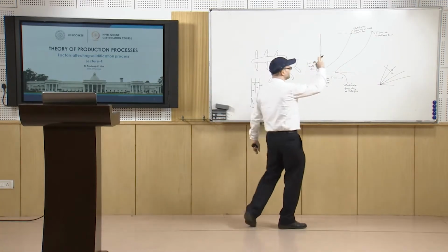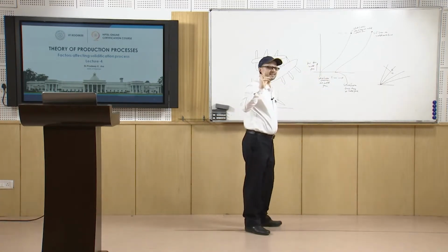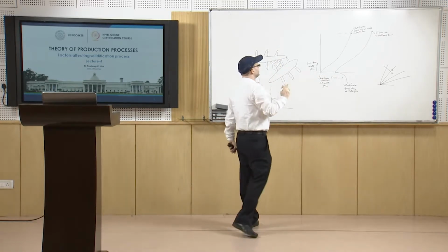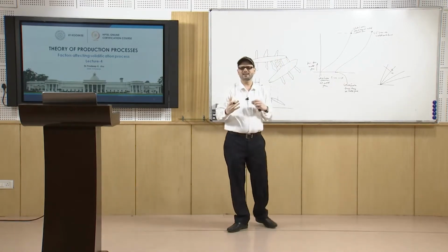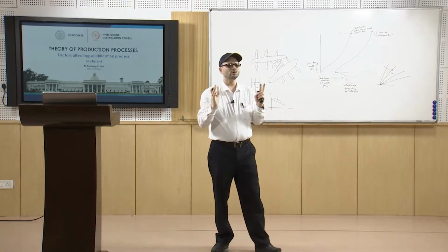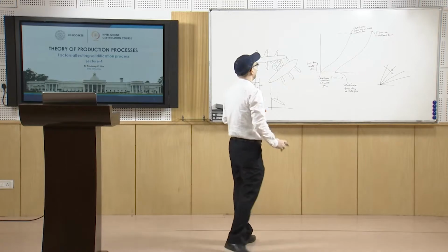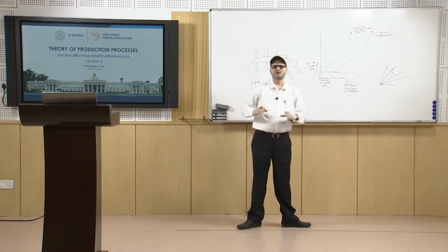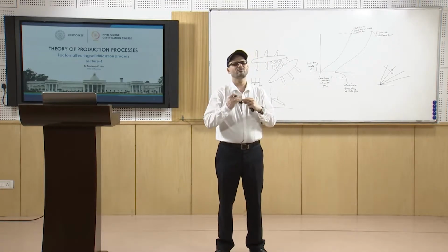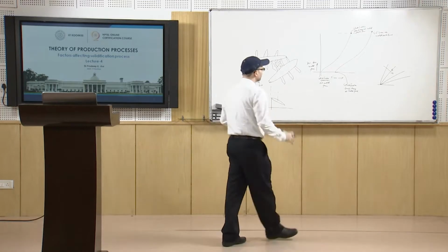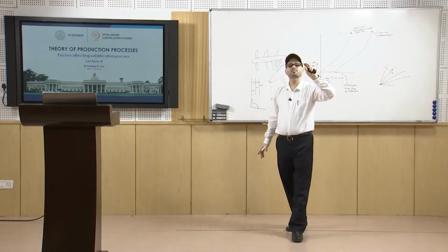Now, what we see here is that it starts here and it finishes here. So there is a parameter which is defined: center line feeding resistance. Why do we call it that? Because when we move towards the center, the part will be more prone to all these kinds of defects. When you have large freezing ranges, as the freezing range becomes more and more in alloys, the situation is more difficult, as you have to feed it properly.